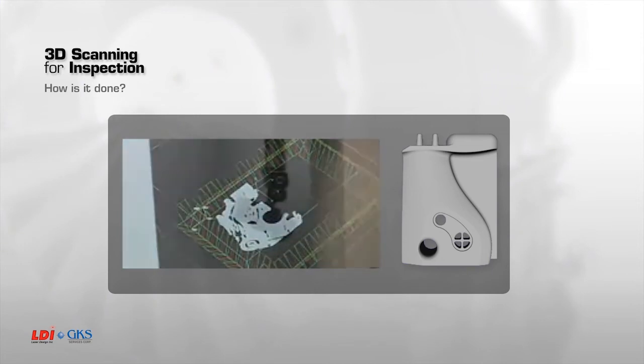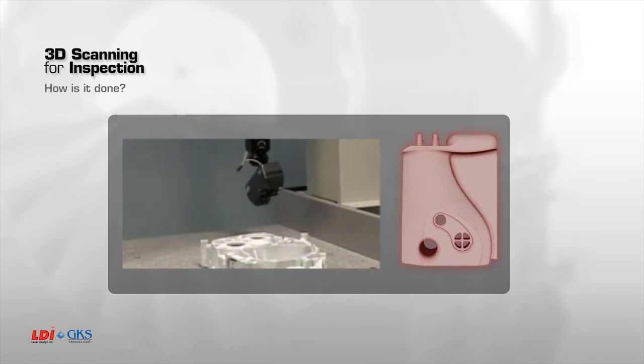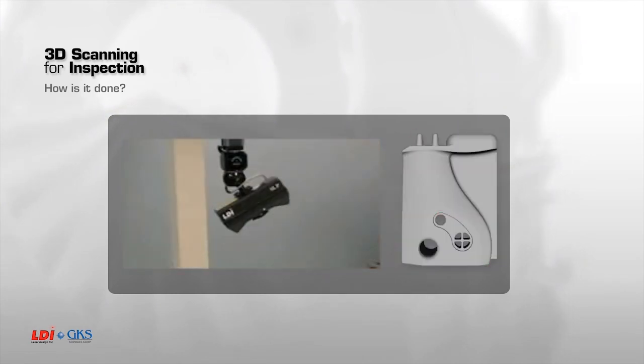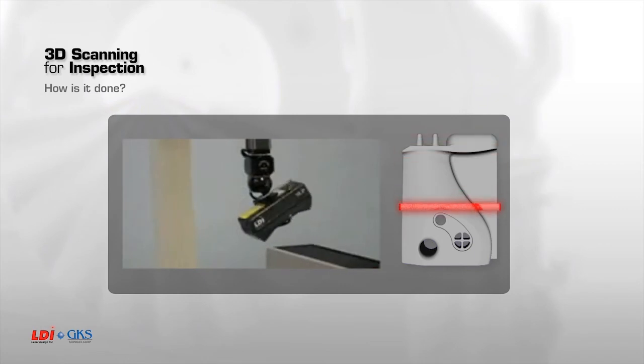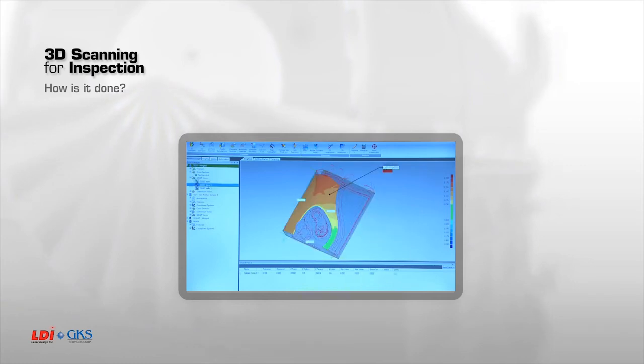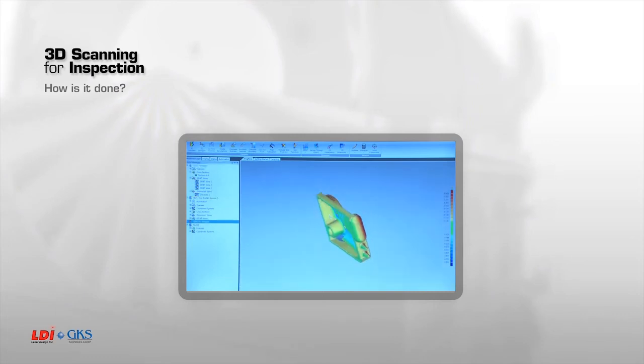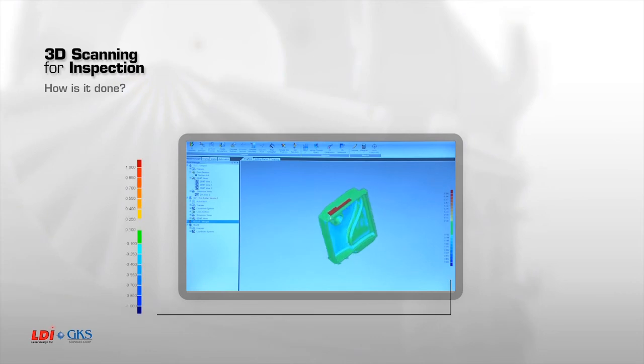The point cloud is superimposed on top of the CAD model, either using algorithms, which do a best fit, or using datums and features which reflect the design intent. Each point is given a distance from the CAD model and is assigned a color. All of the points are taken collectively and merged into what is known as a 3D color map. The colors are keyed to the tolerances shown in the scale on the left. They are blended together, so it's very easy to quickly see where a part may deviate from the acceptable tolerance range, which is shown in green.